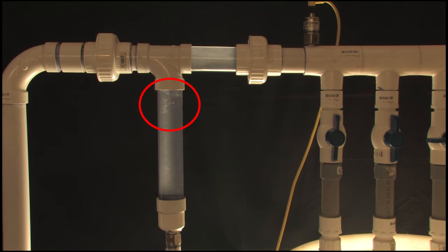But down here, again, we see the turbulence is contained to the upper part of the stub pipe. And if you look close, you can see how slowly the small particulates are moving near the sensor at the bottom of the stub because there isn't any turbulence. I love that demo because you can actually see what's causing the mechanical noise in the sensors and why the 5 pipe diameter rule works so well.